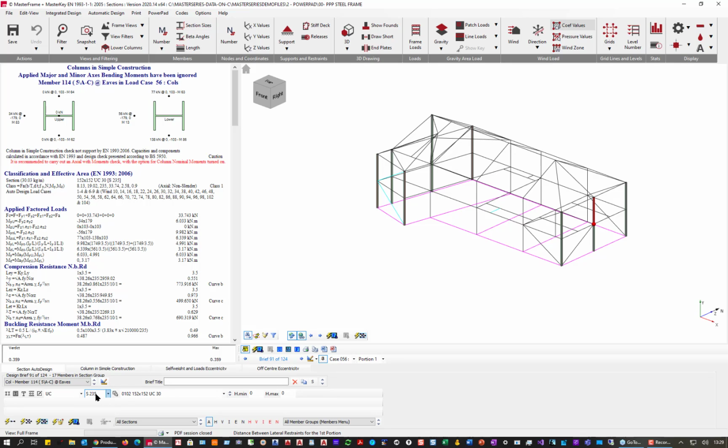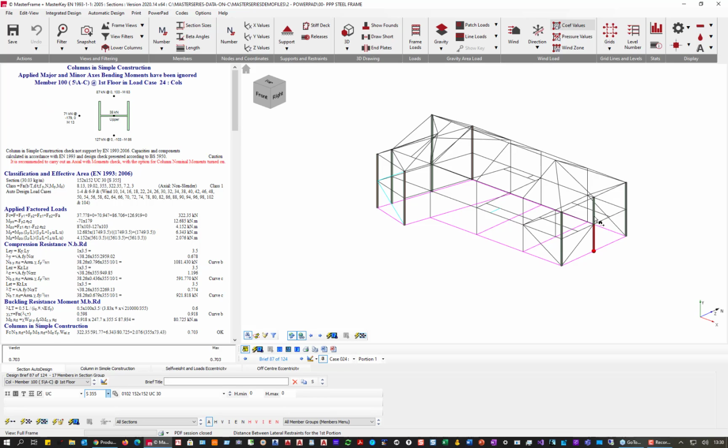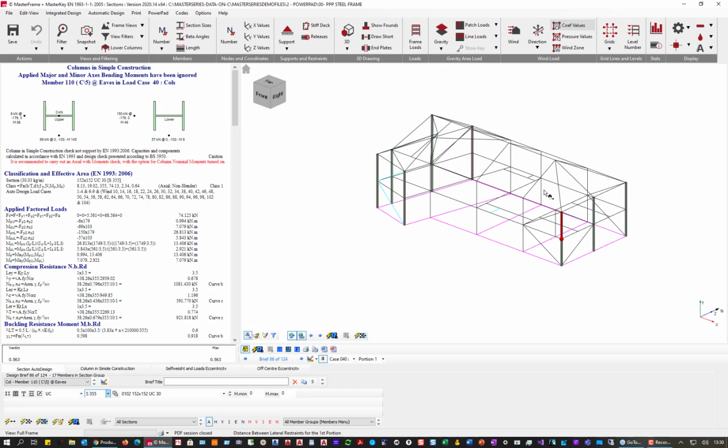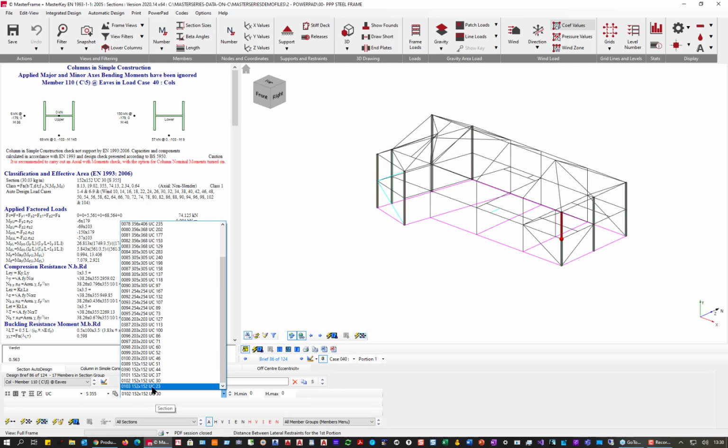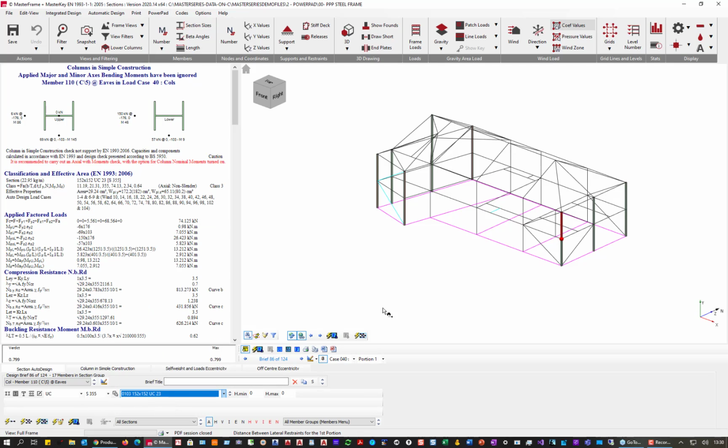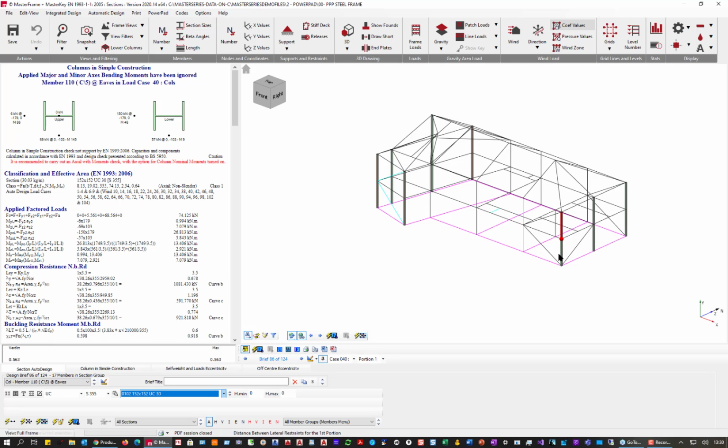So very, very useful. And if I take this back to 355, auto size again, we will see that one of the members is requiring the 30 kilogram anyway. But you get the point. I had it down at the 23 and it's working. I auto size and it suddenly says 30 because it's checking not the one member but all 17 of them.